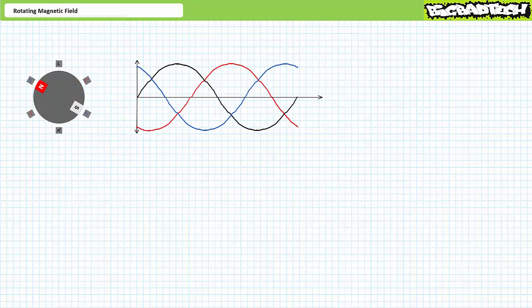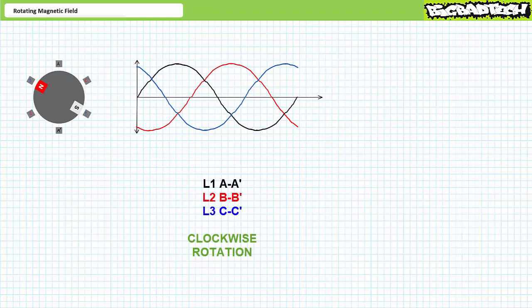Let's now examine how phase sequence determines rotational direction. You'll notice previously connected, L1 to A, L2 to B, and L3 to C, the rotating magnetic field revolves in the clockwise direction. 3-phase AC, in addition to establishing a rotating magnetic field, makes it supremely easy to change rotational direction by swapping any 2 phases. Allow me to demonstrate. Consider this subtle modification and its profound impact.